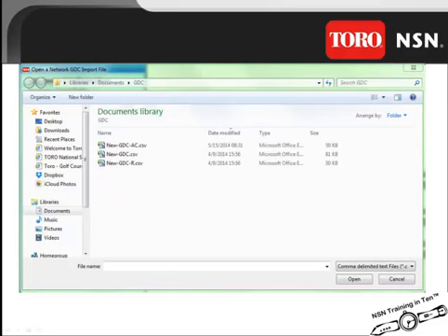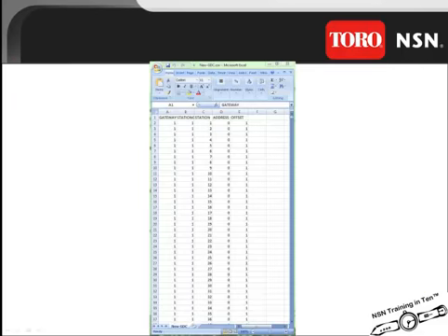All three CSV files are located in Libraries, Documents, GDC. When utilizing Lynx Quick Start, it will take you to this location when you click Import Stations. All CSV files are very similar. You can input the gateway numbers, the station group numbers, the station number, the decoder address, and the offset prior to programming. Or, in the operational portion of Lynx, you can update those as well.